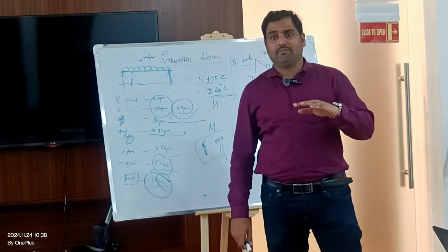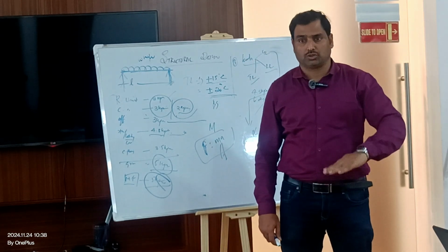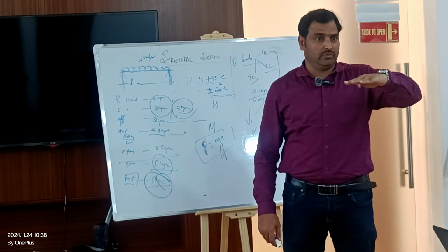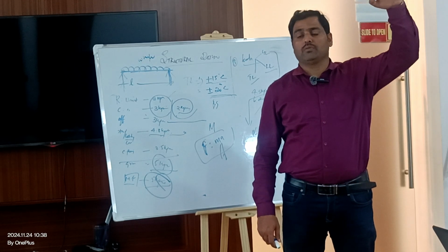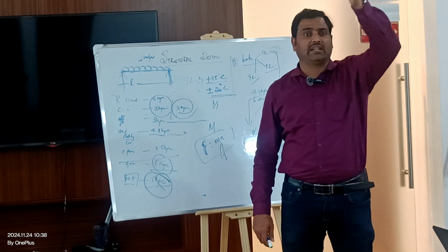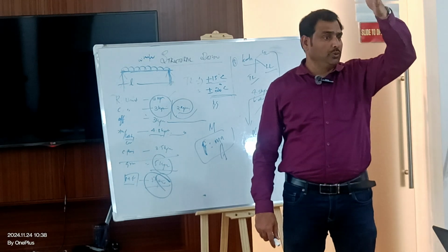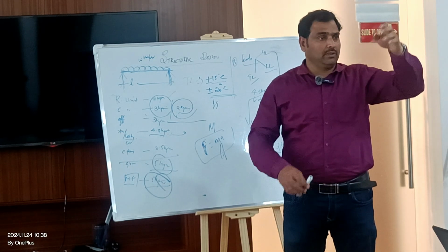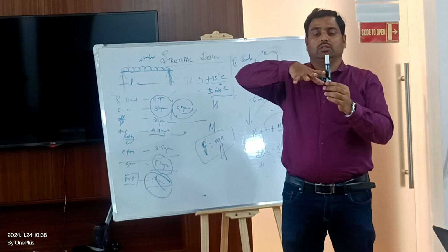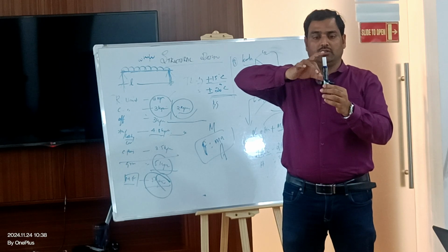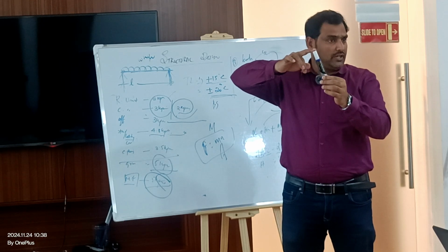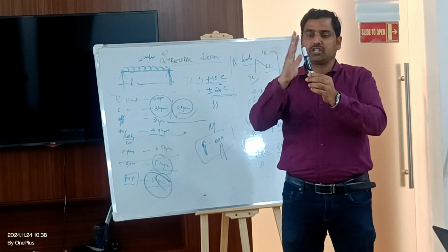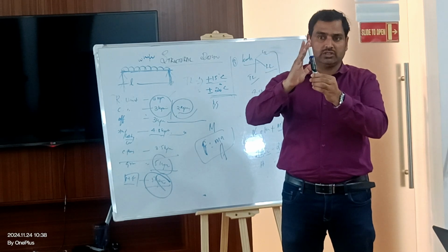So you don't have any problem for the lower structures, like up to 3, 4, 5 floors. There you will have a problem where the maximum drift is damaging. When the building tries to expand and displace, then this tower and that tower collide with each other.